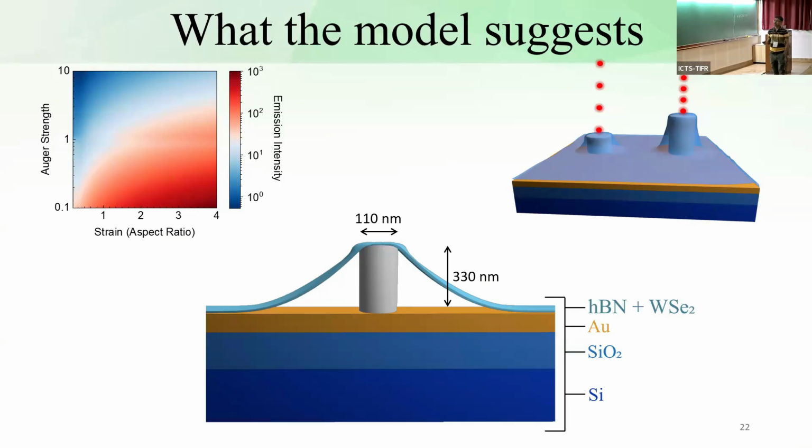So even if you look at literature, often you see that these pillars are silicon pillars or silicon dioxide pillars, and they are very hard. The problem with these hard pillars is that you are talking about a very tall pillar, and when you put this monolayer on, often they punch through. If you actually punch through, it becomes a mess, and there are too many defects. You don't want too many defects. You need to be at some optimum point, right? So they just don't work.